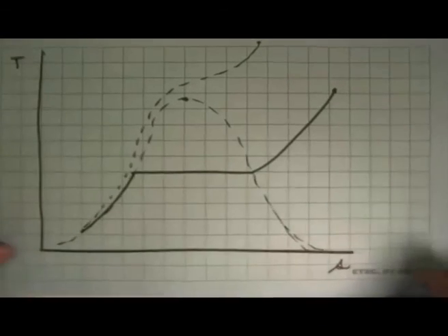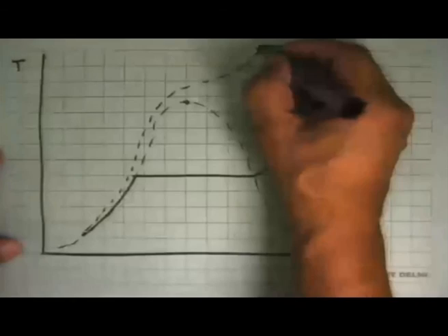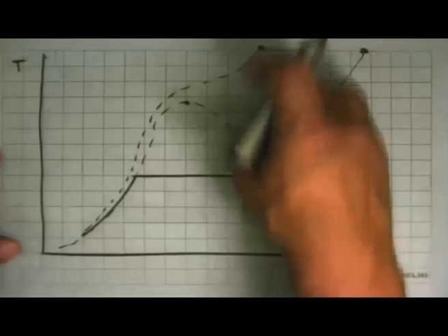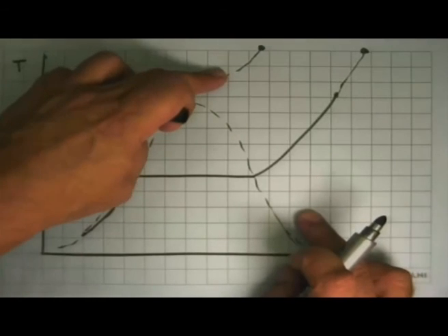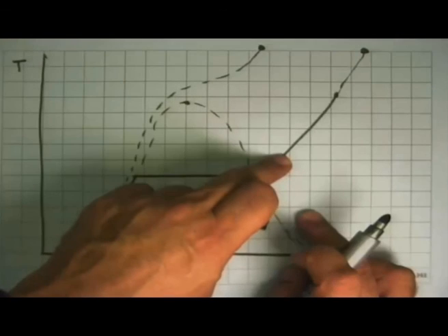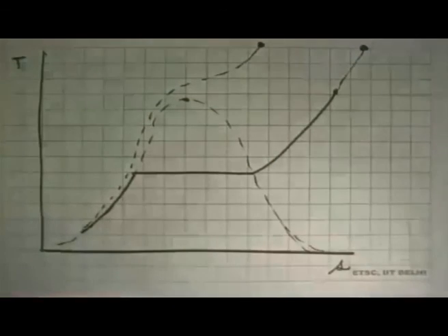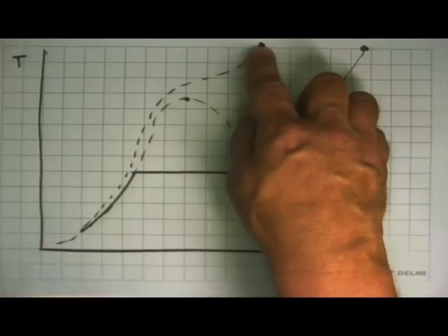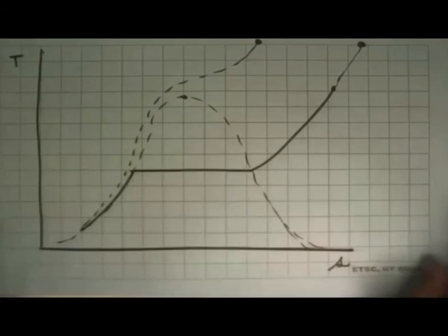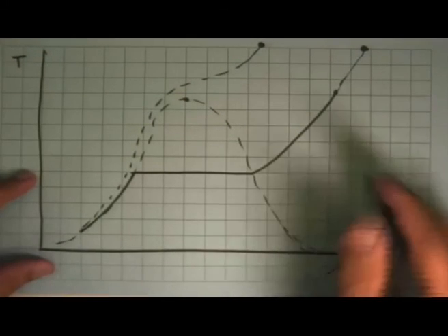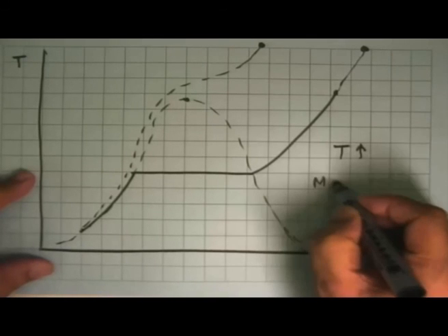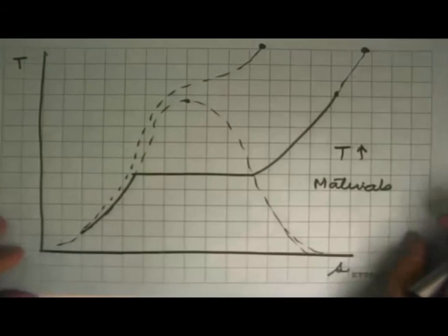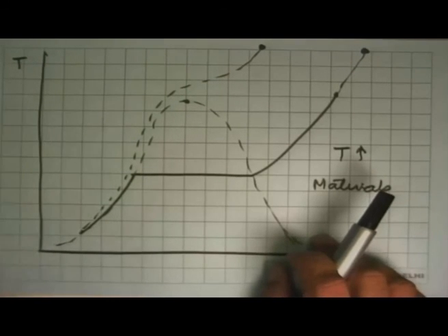And the reason why we design it is that when you use steam at this condition versus steam at this condition, the thermodynamic efficiency of a cycle built around this is going to be much more than the thermodynamic efficiency of this cycle. So that is the reason why traditionally pressures have gone up, temperatures have gone up, and we are coming to supercritical pressures and temperatures. The limiting factor though, thermodynamics tells you can go as high as you want in temperature, but we do not have materials for making a boiler that can withstand such high temperatures at high pressures for 20-30 years. That's the challenge.